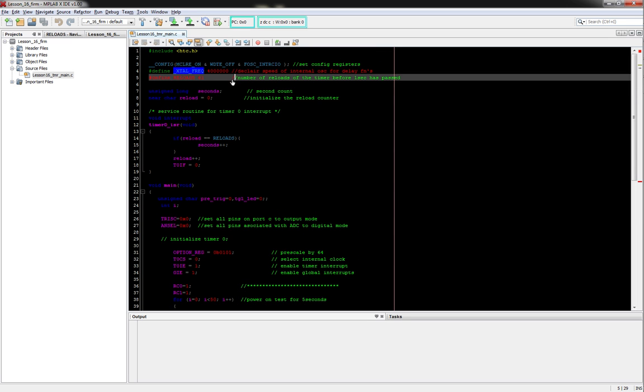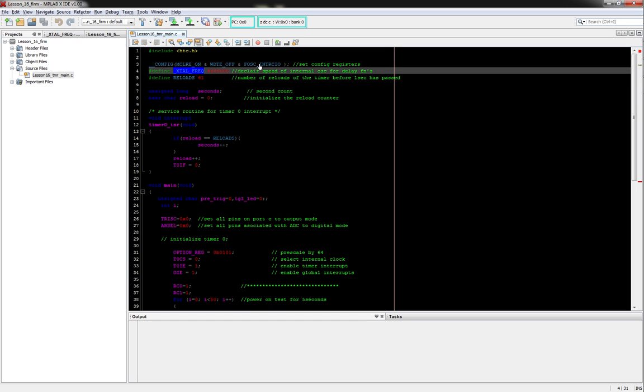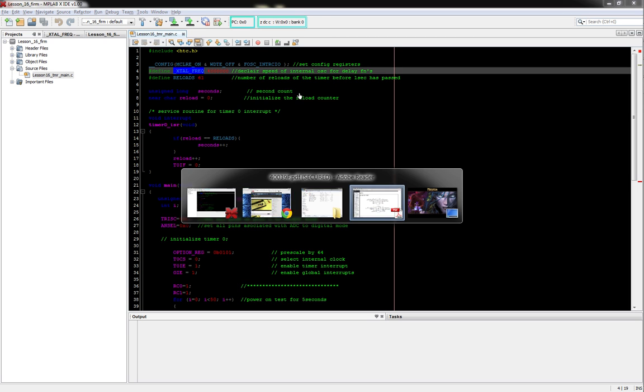So if you use an internal oscillator, and the internal oscillator by default is, let's say, 8 megahertz instead of 4, then your timing is going to be way off, because you're thinking that it might be 4 when actually its default is 8. So you could be off. So make sure, and you just got to read in the data sheet. The data sheet has that in there. In fact, I might be able to show it to you.